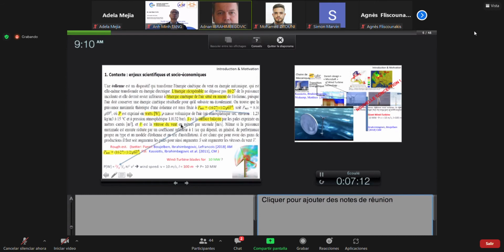But a very rough estimate says that out of all the wind power produced by, let's say, wind blowing at a steady speed, you can basically recover 16/27. If you take into account that the density of the air in a dry atmosphere is roughly 1.23 kilograms per cubic meter, you can say that roughly you can recover 2/3 of what is really entering as the wind.